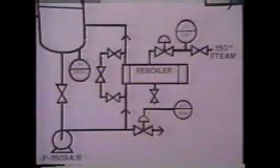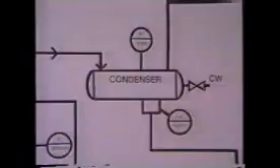This long-term procedure differs from the short-term procedure in that all the equipment is shut down and the materials are removed from the system. The final shutdown procedure we'll look at is the emergency shutdown. There are several types of emergencies that would require shutting down the system. For instance, there might be a boiler failure causing a loss of steam to the reboiler or the vacuum system. Another reason would be a failure in the cooling tower that provides chilled water for the condenser.